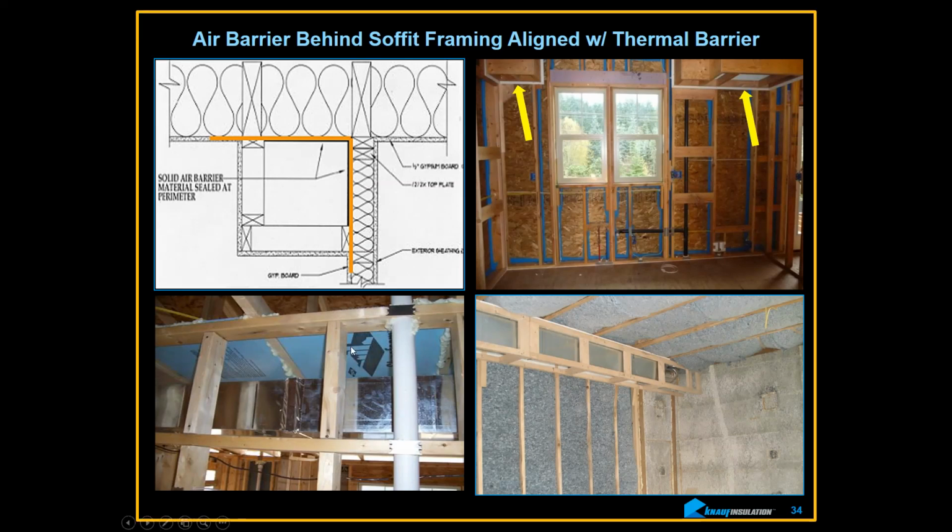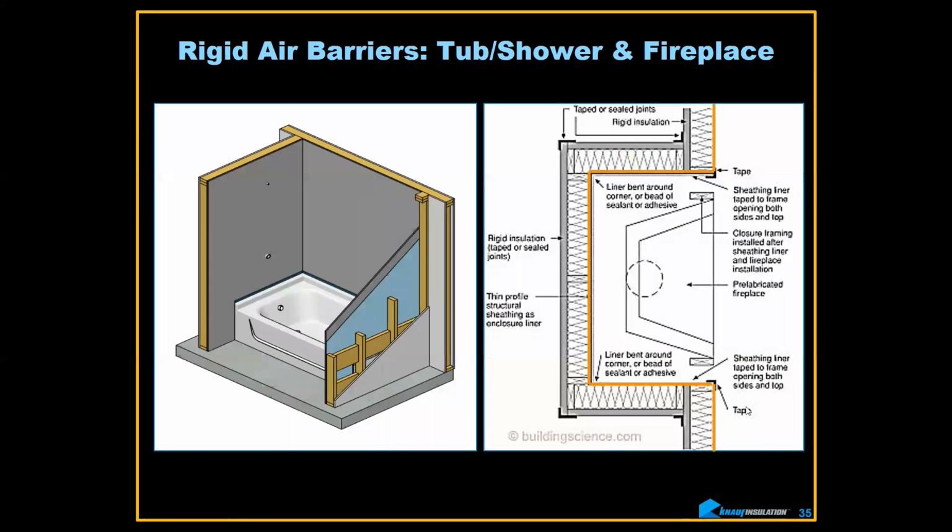This one's not as good because the blue board is held back, which means there's no way for him to hit that seam. He can only hit it on the outboard side of his drywall. He can't clear it in here. Same thing here. It's too far back. They can't cover their seam. They had the right idea, but again, the detail of the details. You got to think ahead, otherwise it won't work.